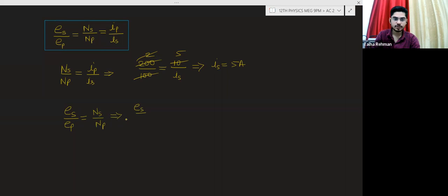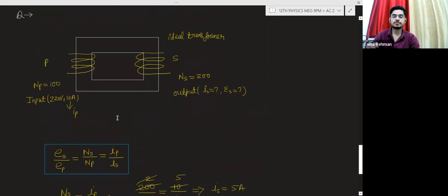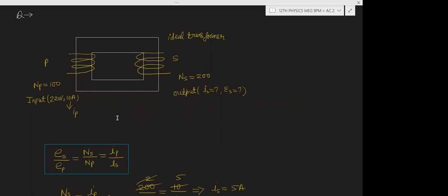What is EP? 220 volt. What is NS? 200. What is NP? 100. So when you cancel this out, finally you will get ES as 440 volts. Hamza, take the screenshot of this question. Yes, sir.